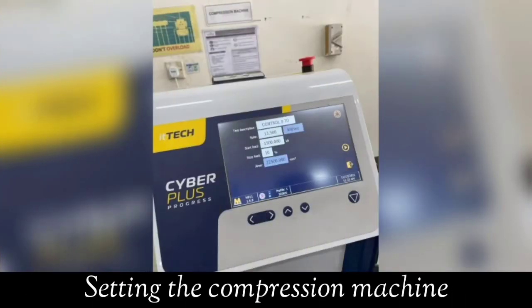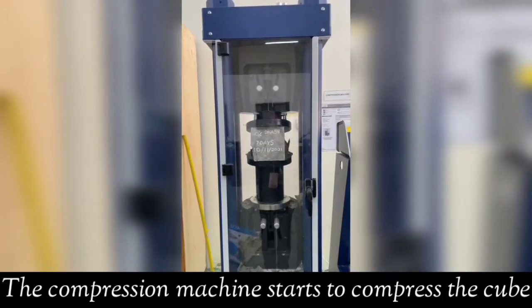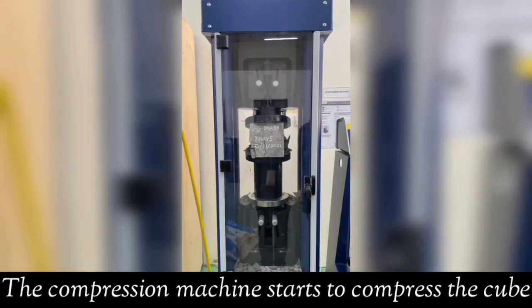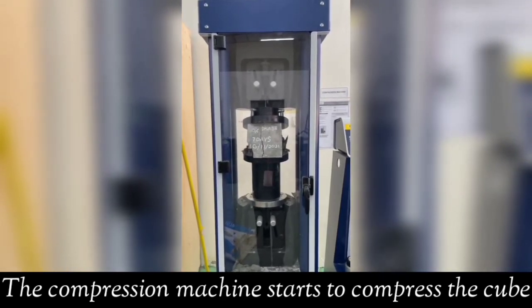150 kN load is applied gradually without shock and continuously at the rate of 13.5 kN per second until the specimen fails. The compression test has started and the load begins to crush the cube. The maximum load is recorded and any unusual features in the type of failure are noted.